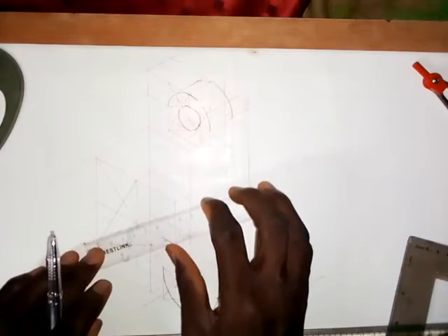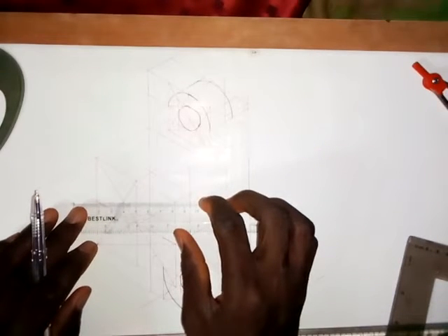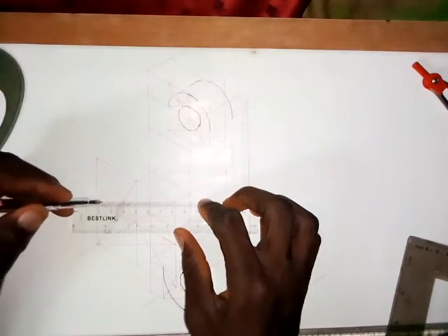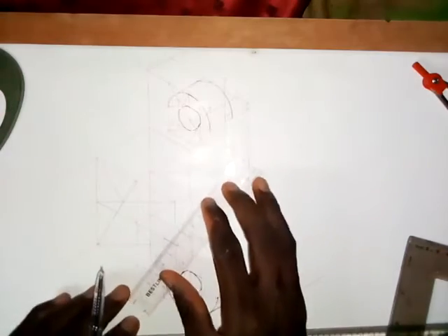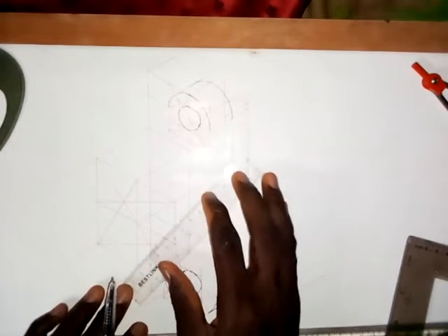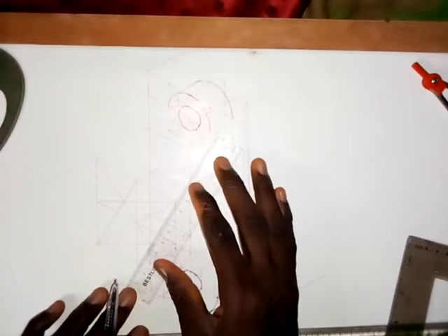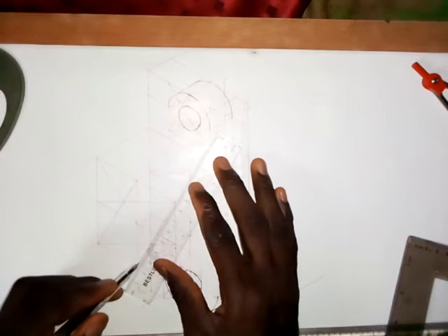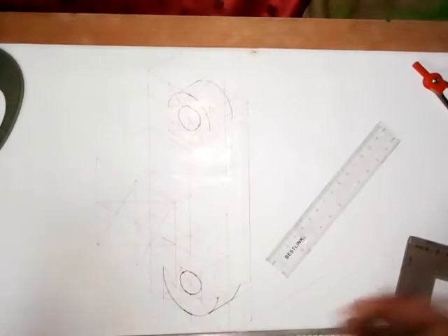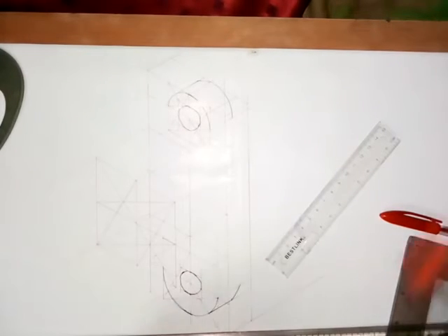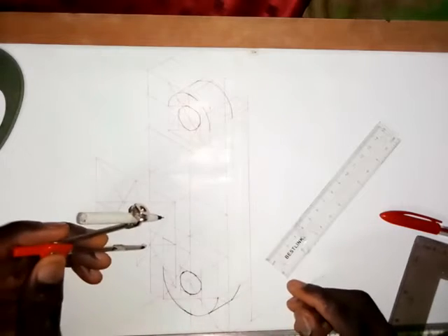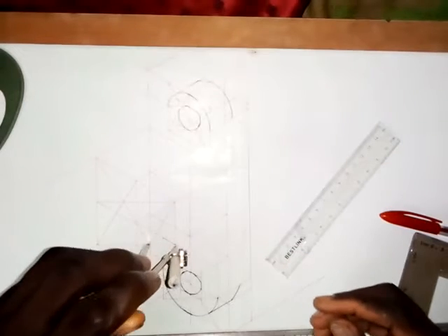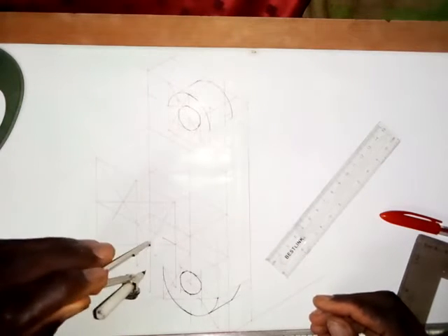So also, I'm going to join this. When you watch my video on how to draw an isometric circle, you will have no problem in locating the points. So please go and watch the video. I'm using the 4 center method to draw the isometric circle. We also have other methods, but this is quicker. So I'm going to put the pinpoint of my compass here, and I will extend to this point, then I will test it.